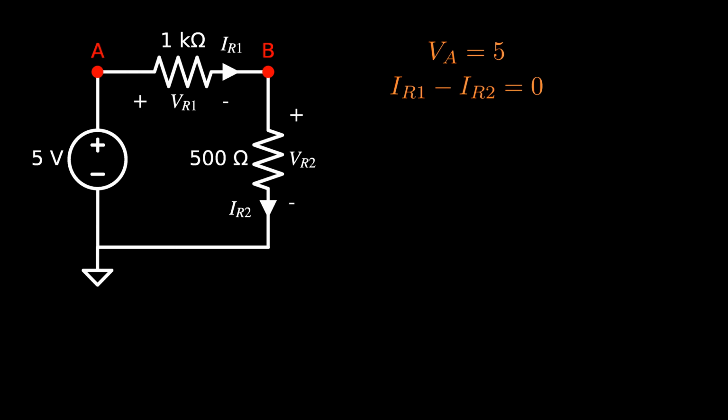We can add resistor voltages respecting the passive sign convention. The positive side of the voltage is on the tail of the current arrows, and the negative side of the voltage is at the tip. We then use Ohm's law to replace each resistor current with terms expressed with resistor voltages. The resistor voltage in the numerators can be replaced using simple KVLs. The node voltage on the positive side minus the node voltage on the negative side.